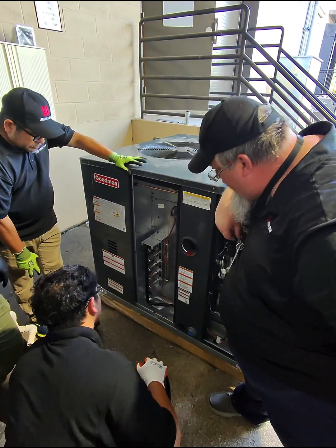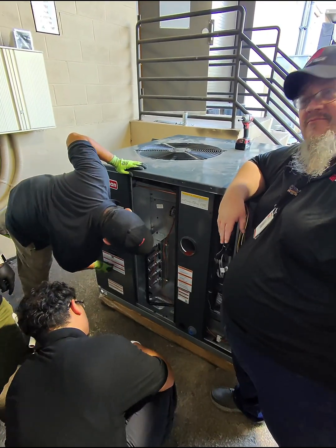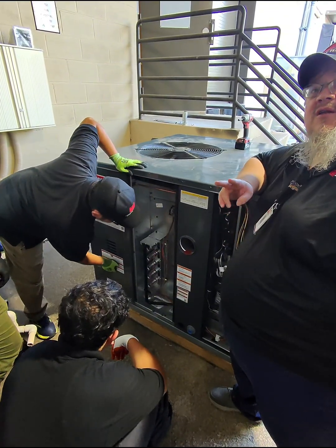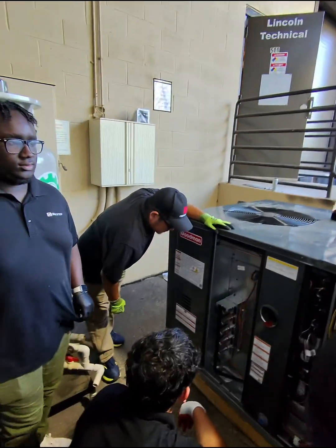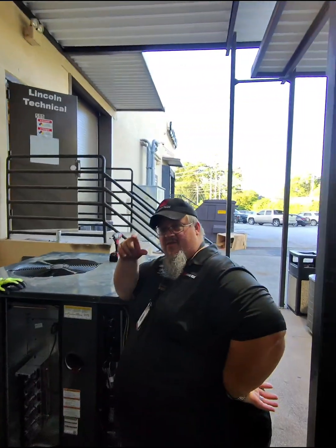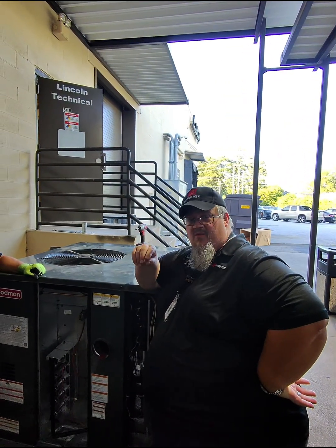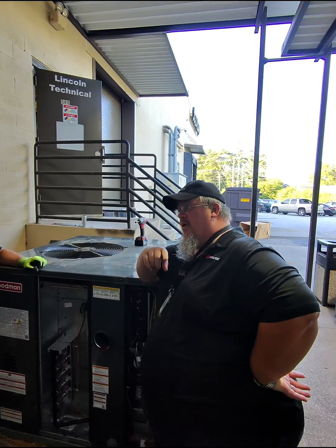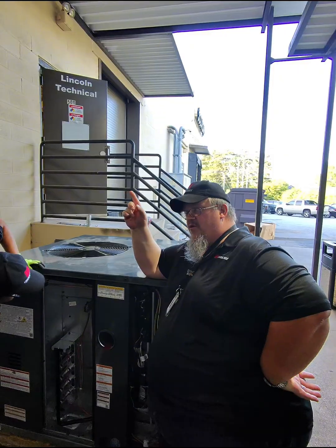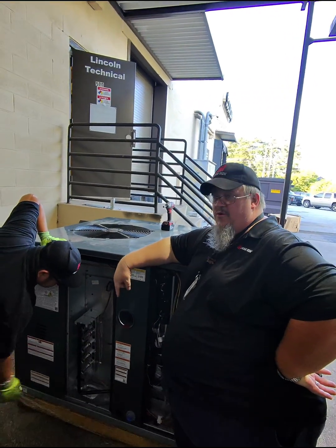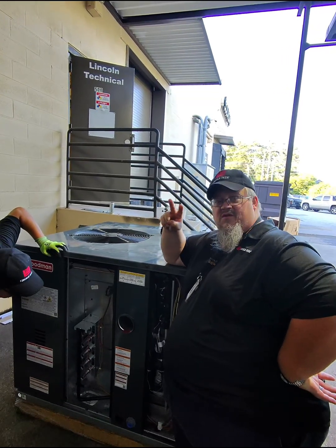How do you know what's what? And what type of igniter is it? How many types of igniters are there? I think we got two, right? There's one that's gas with a standing pilot, which on our furnaces you won't see much anymore. That was old school. You will see water heaters or space heaters that have thermocouples, but the vast majority in our trade, you're going to have two primary types. What are the two types?